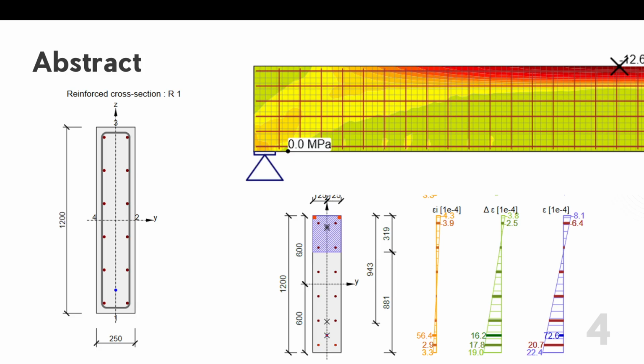On the other side, detail has a different philosophy. It's a 2D plane stress model built on the compatible stress field method and continuous stress fields, in which equilibrium and compatibility are solved simultaneously across the entire region. Crucially, it accounts for tension stiffening directly in the reinforcement behavior.